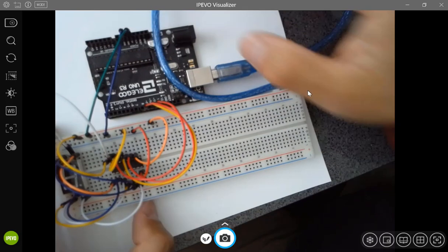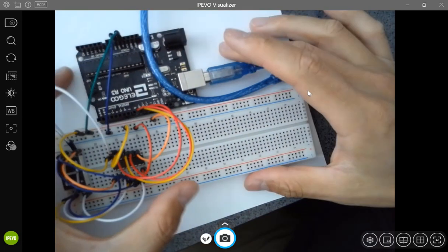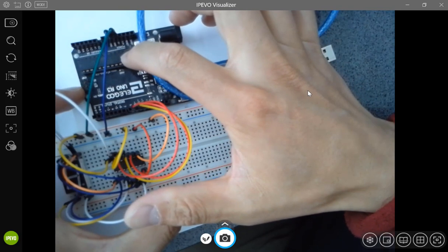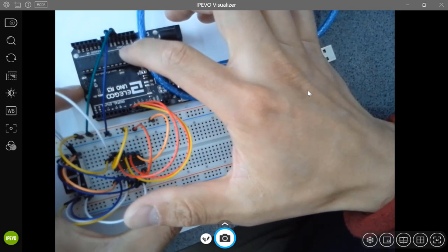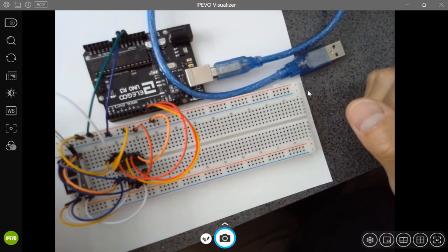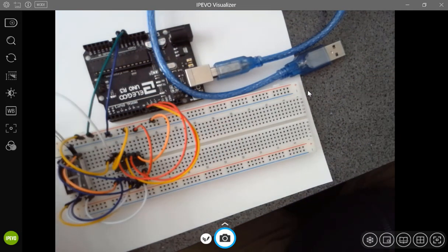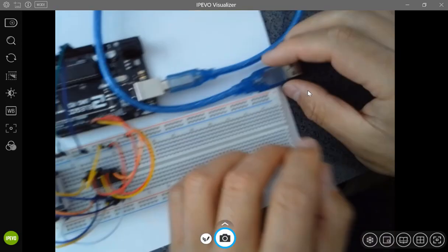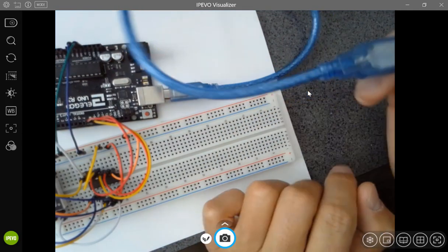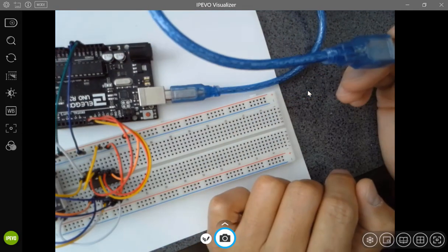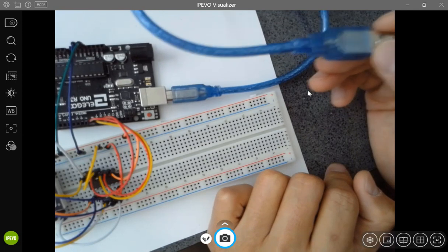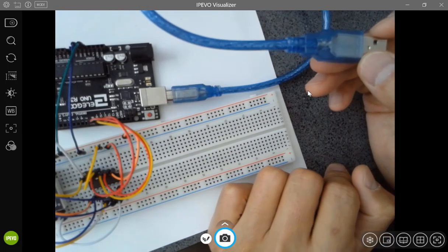One thing to keep in mind, I'm going to repeat this in the future a lot, okay? This is a digital device. You agree with that? It has digital pins, high and low. Low is 0 volts, high is 5 volts. The reason you are getting 5 volts is because you plug this into your laptop, and your laptop is sending the 5 volts through the USB to your chip. Where does that 5 volts come from? From the laptop.